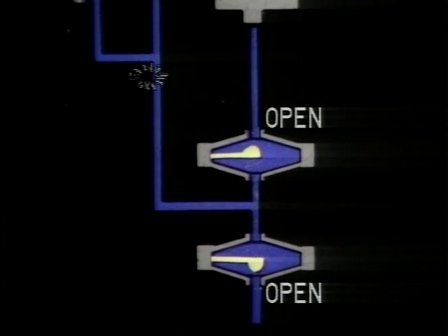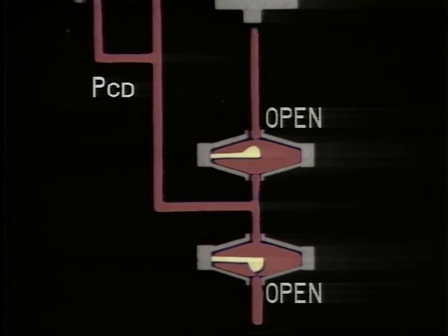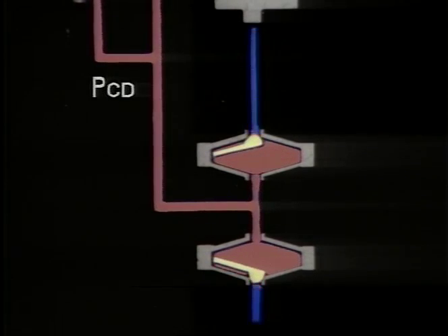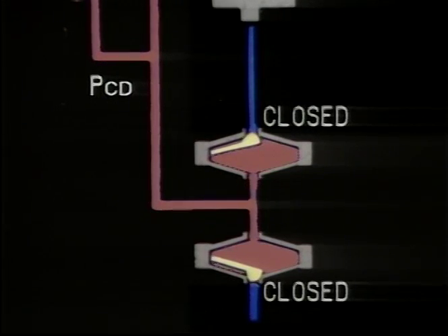During startup, PCD eliminates any residue that may be present in the combustor by blowing it out of the drain valves. During engine operation, combustor pressure of 3 to 5 psi closes the valves to prevent bleed action.